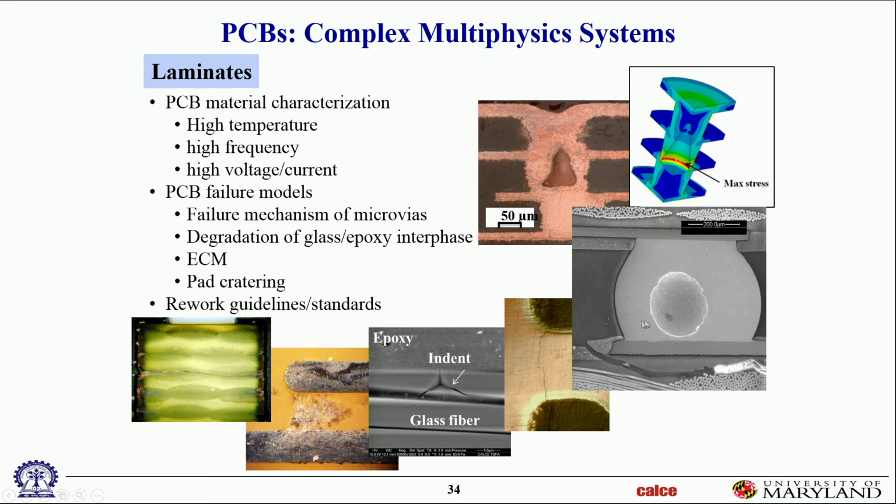This is another kind of failure. This is a ball solder joint. It has a big void in it. Interestingly, the void didn't cause any problems. It survived the void fine, but if you look carefully enough, it has ripped out from the circuit card. That happens a lot in high temperature solders. The printed circuit card cannot withstand that soldering temperature and initially gets damaged, and then that becomes a weak point.